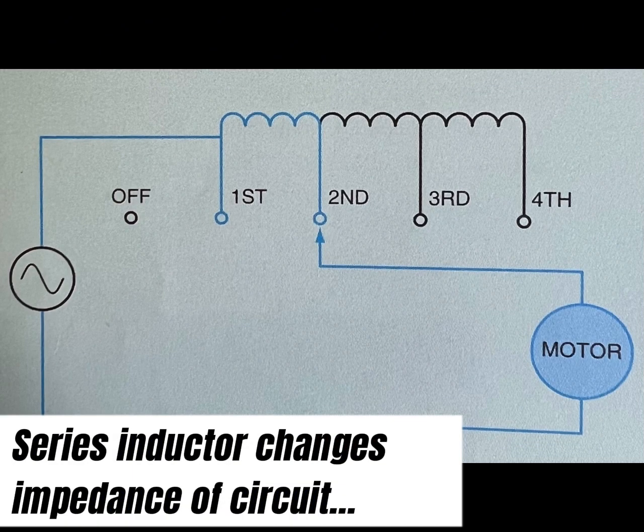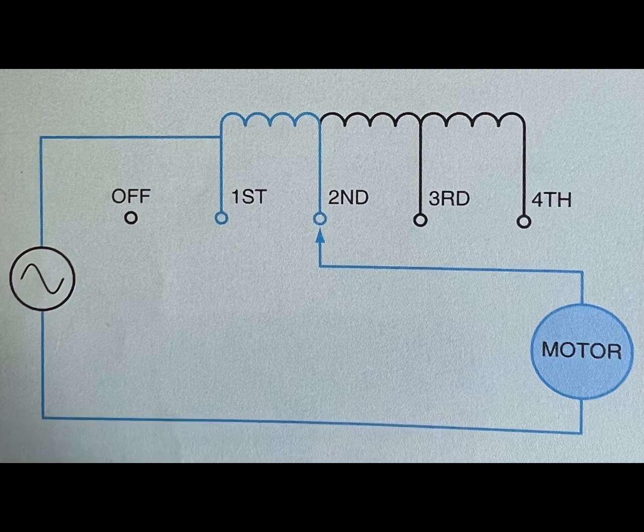Triac circuits intended to control incandescent light loads will often conduct on one half of the AC cycle and not the other. For example, assume the triac in the above image turns on during the positive half cycle of voltage before it conducts the negative half cycle. A waveform similar to this would be produced across the load.